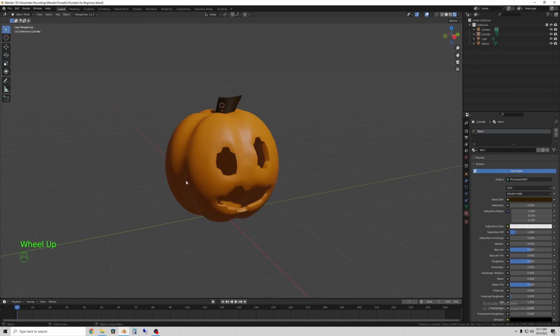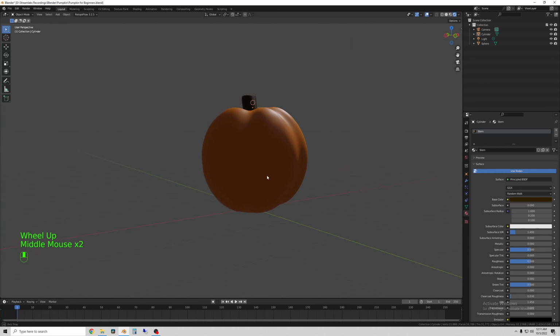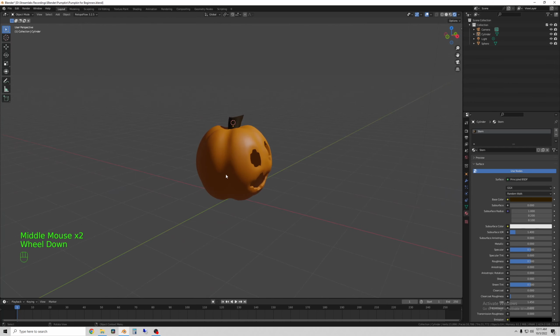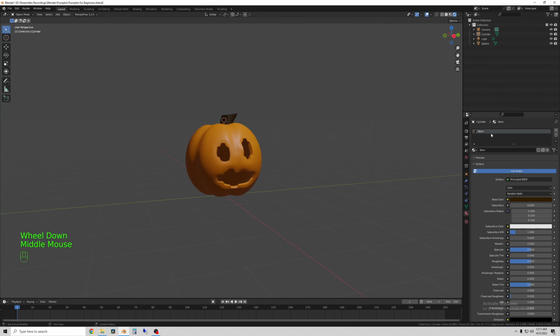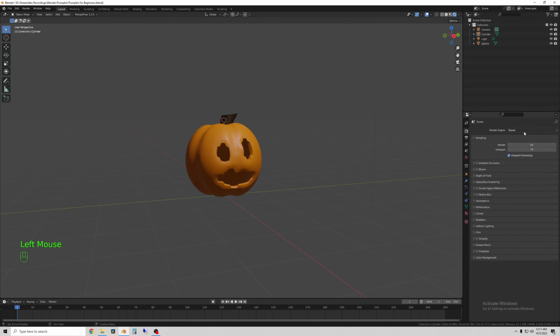And you can see some of the shadows look a little more realistic now, but nothing really changed. Well, we're still in the preset renderer, Eevee, which is a fast, kind of more toony render engine. Sometimes it's not always toony, but what we want to use is Cycles. So switch to that.